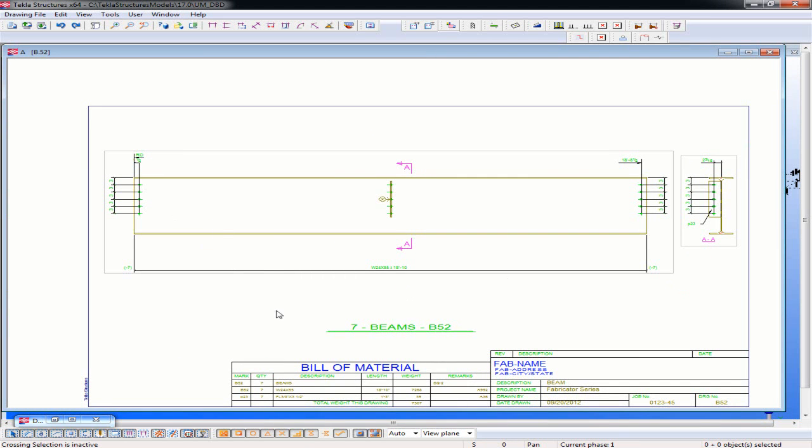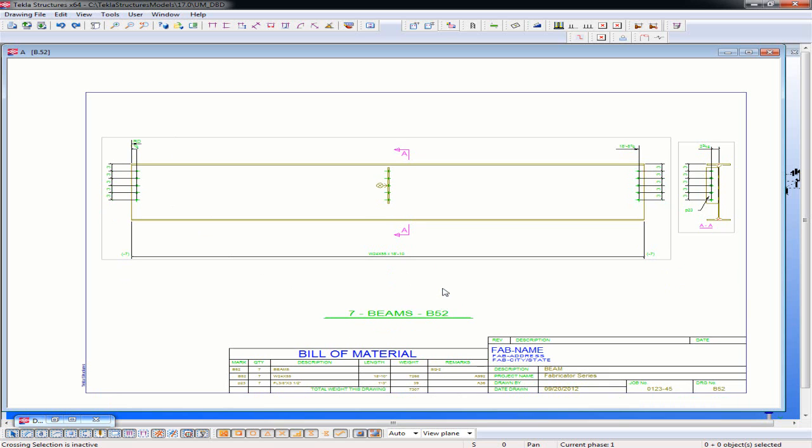So here you can see this piece, the bill of material already exists. You can view this in color or in black and white just by using a selection on your keyboard. But you'll notice here that we didn't locate where this shear plate was. There's no running dimension or anything like that. I have a section, and you also notice that the weld information is gone. So this is real nice if you're a fabricator and you're in the middle of fabricating something and you can't get a hold of the detailer, or you don't have time to submit an RFI or whatever.